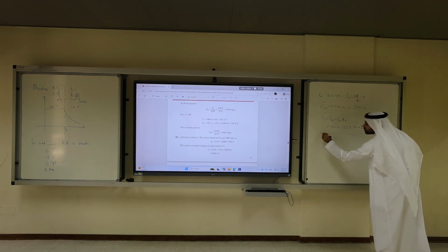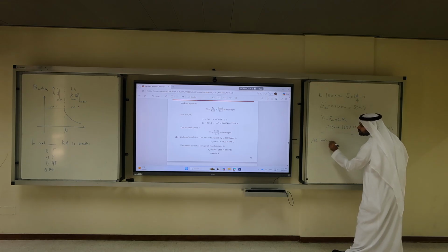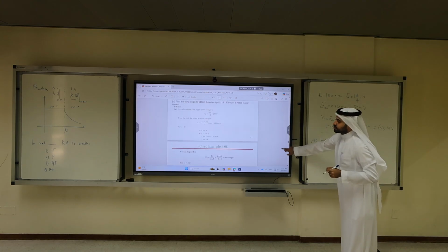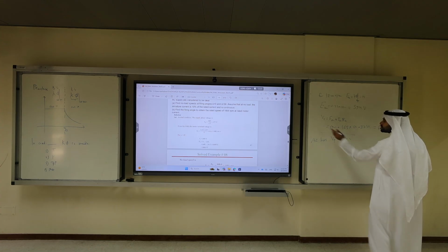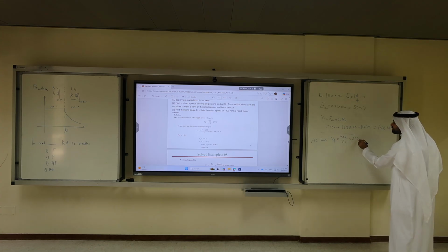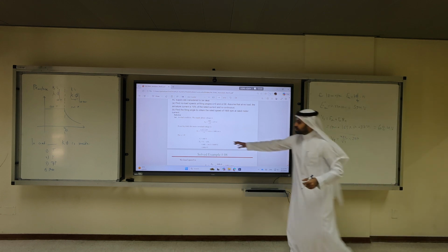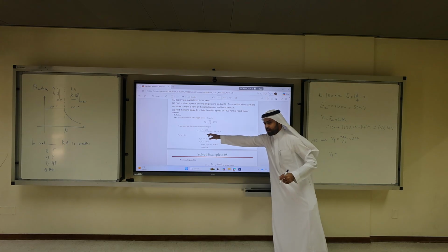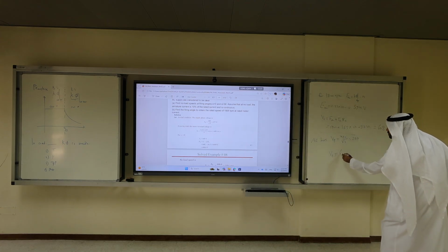So now, the AC has VP equal to what? 480 over square root of 3, which is 277. Vt equals, what's the constant? 648, which is 3 times square root of 6 times 277 over pi, which is 648 cosine alpha.